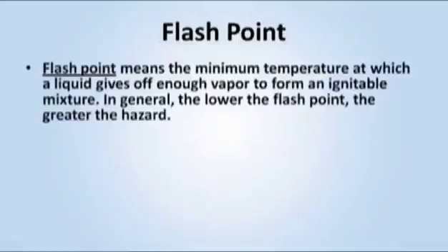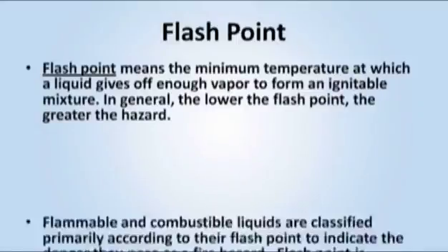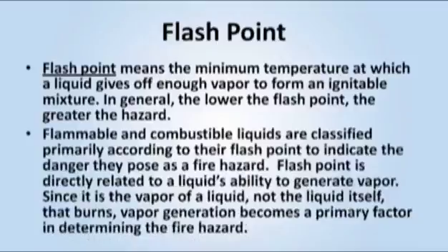Flash point means the minimum temperature at which a liquid gives off enough vapor to form an ignitable mixture. In general, the lower the flash point, the greater the hazard. Flammable and combustible liquids are classified primarily according to their flash point to indicate the danger they pose as a fire hazard. Flash point is directly related to a liquid's ability to generate vapor. Since it is the vapor of a liquid, not the liquid itself, that burns, vapor generation becomes a primary factor in determining the fire hazard.